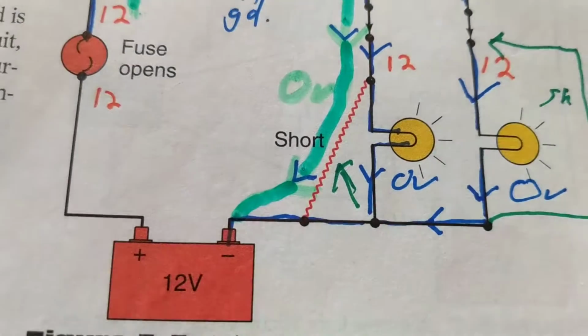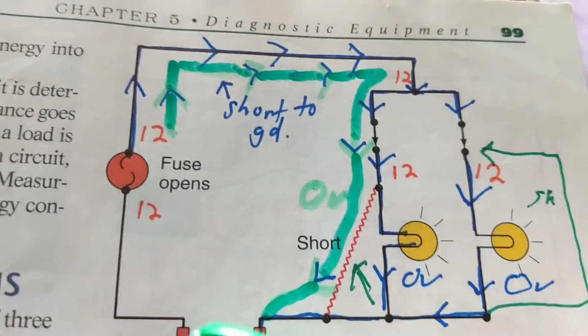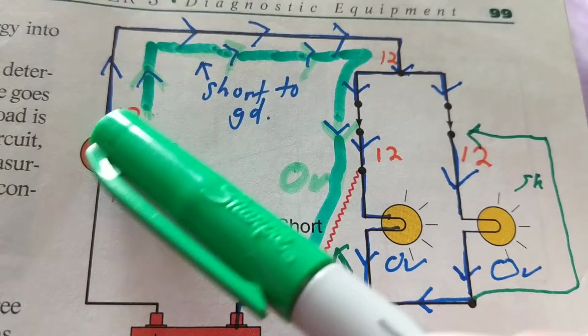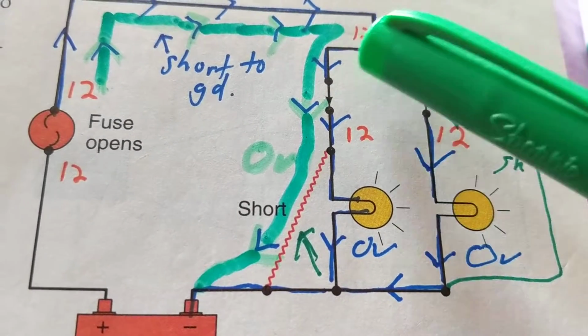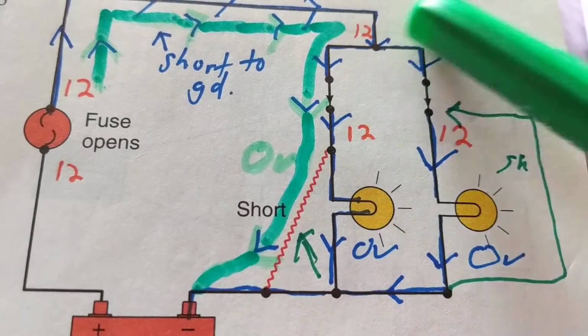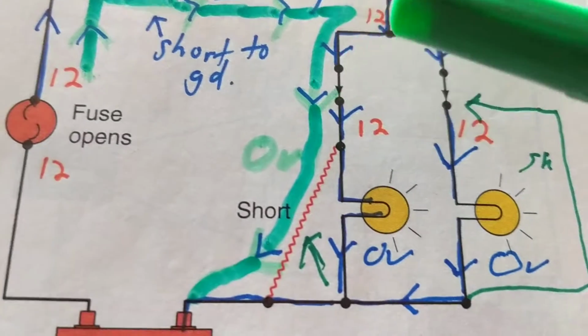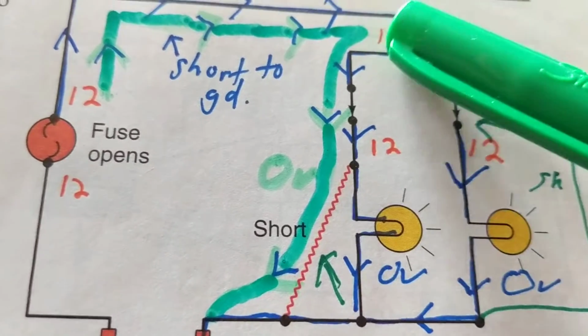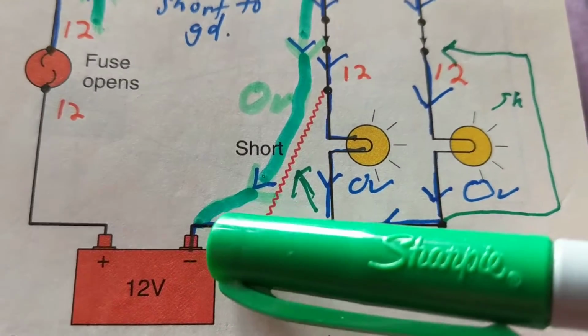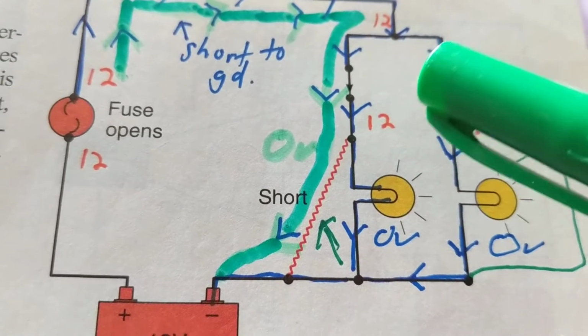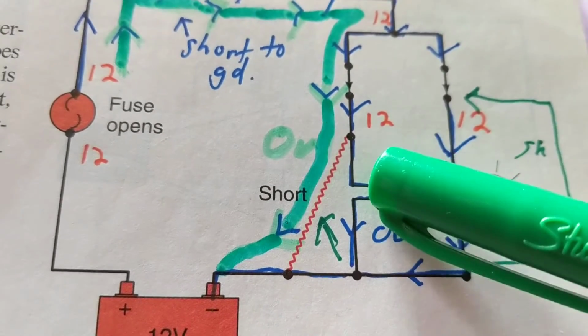Now, we go over here. We know current flows through the fuse. One side comes out the other side. The current splits up because there's two paths for it to go, some here and some here, equal. So let's say 4 amps, whatever, 2 amps here, 2 amps here, and back to the battery, the negative. Time for a short. Let's say we have a short across it.